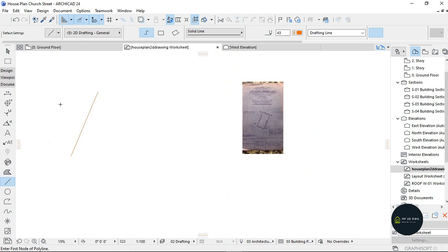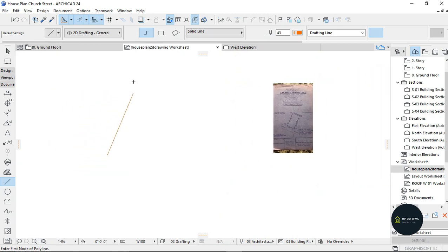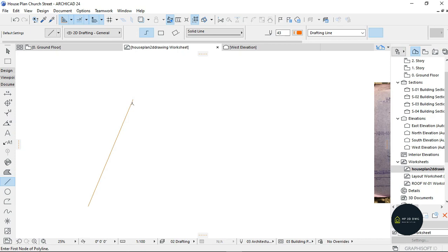And mind you, we're not using meters. So I'm going to click on this edge here, from this point here, and drag it up. Make sure you always drag it up. Once you drag it up, then go to tab and change the angle, which here is 112 degrees, spacebar, 12 minutes, and you press minus.